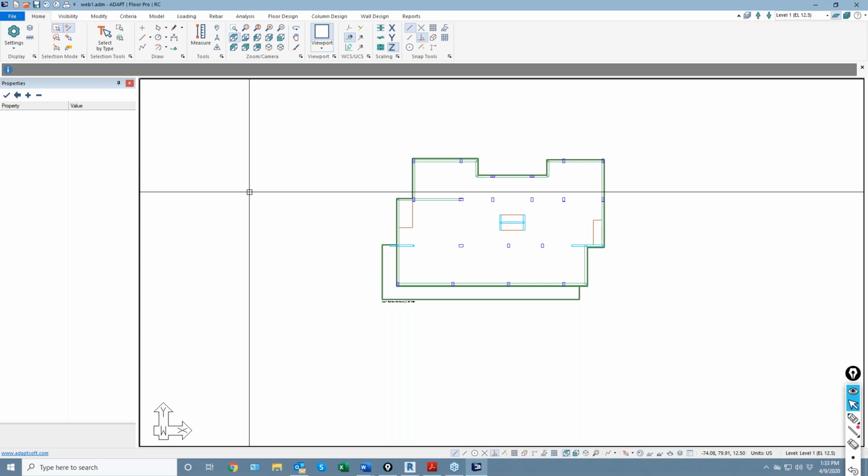All right. One of the most critical aspects of obtaining a design in any slab, whether it's PT, RC, with or without beams, is the ability to generate design strips. So we could go and mesh this slab and analyze the slab and get what I call raw or just basic FEM results for the slabs. We could get deflection contours, frame actions, shell actions, etc.